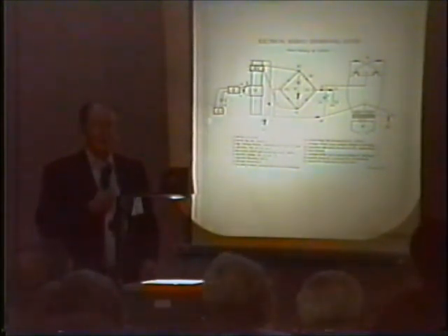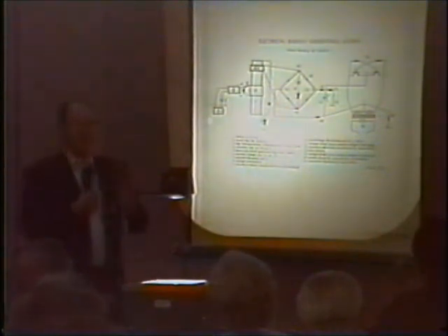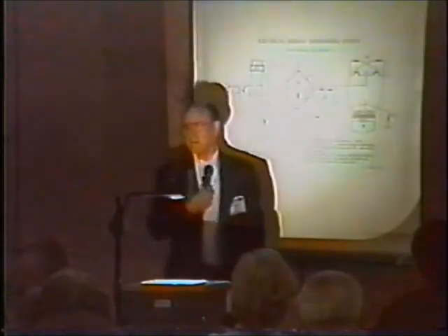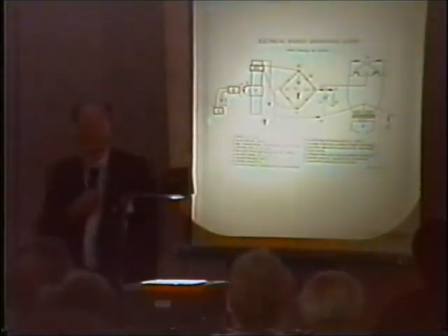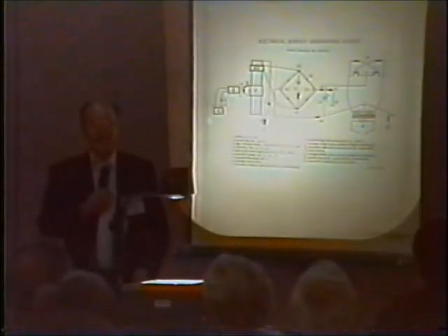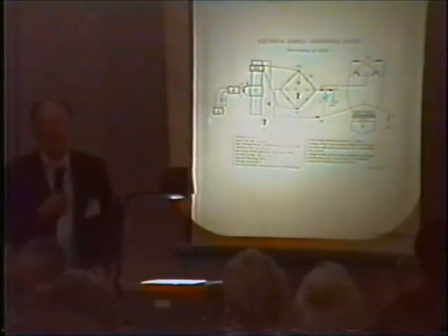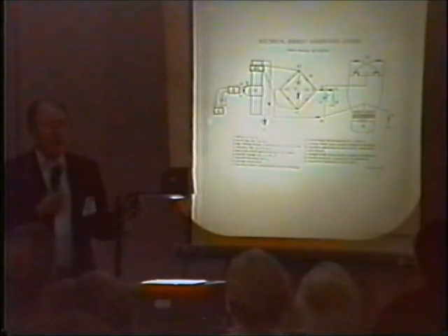And they've got some other characteristics which change it, and these transistors here have capacitance and inductance too. So if you're trying to balance up your impedance on something like this, you can be balancing all day long and a lot longer than that and still not get anything. You've shot yourself out of the water unless you just happen to luck into it.